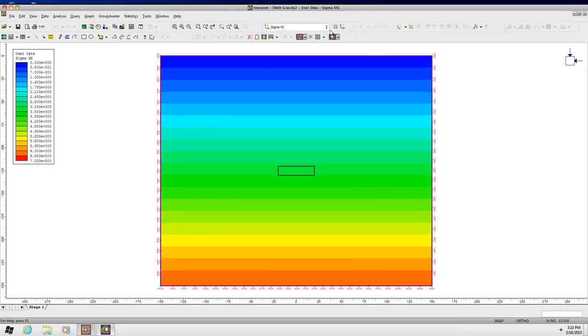Okay. So then you carry out that simulation like you normally do, and you go over to the Results tab. And the first thing you want to do in any simulation is check that the initial conditions are correct and they are exactly what you intend them to be. Because if you don't have it set up right, this is the easiest way to figure out if you have made a mistake, because it's a very simple configuration. And that'll allow you to debug it very efficiently.